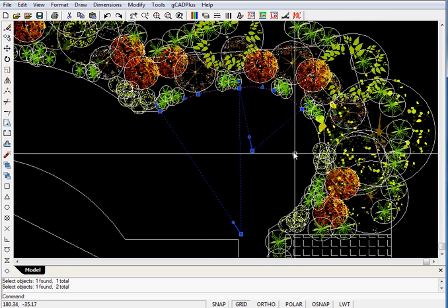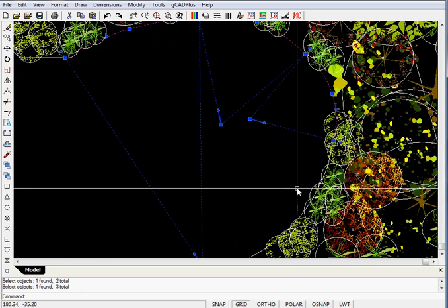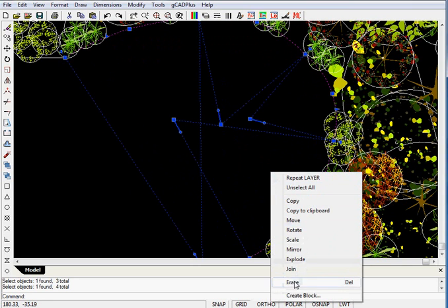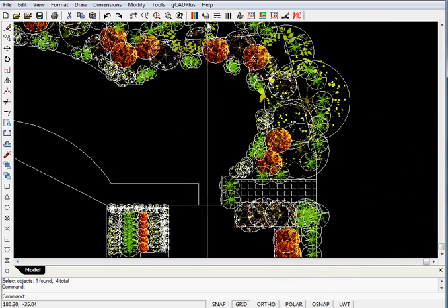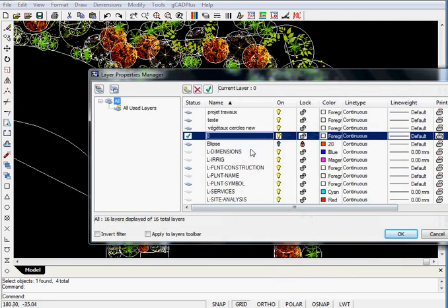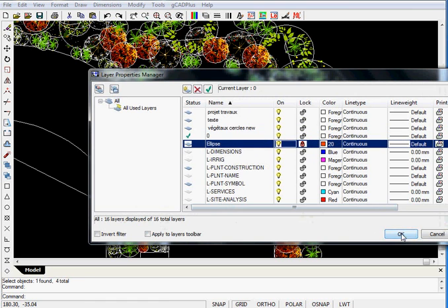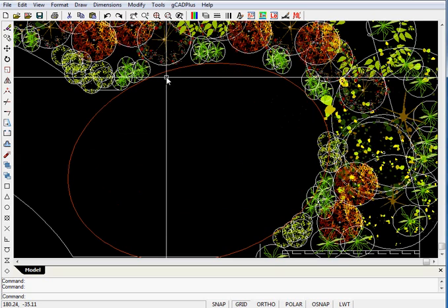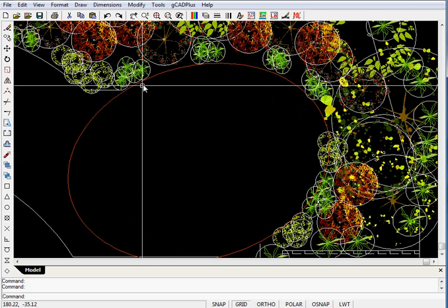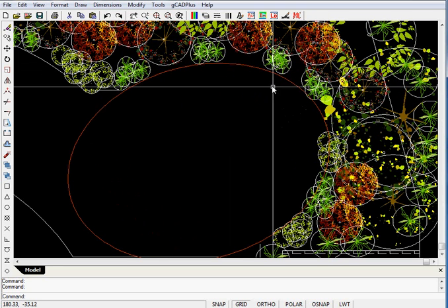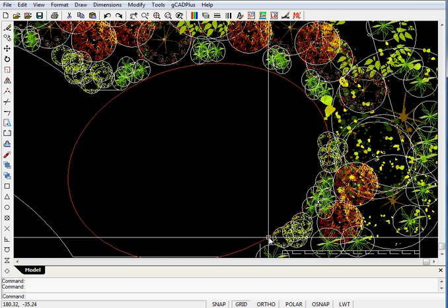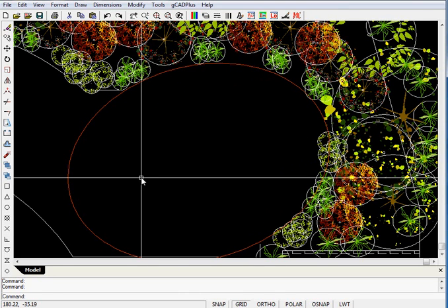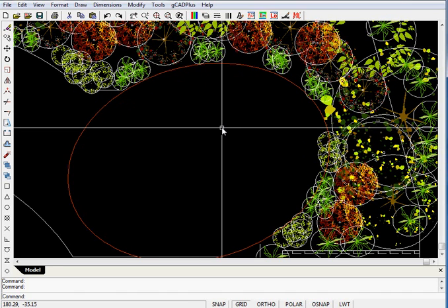So let's remove all of the arcs that are presently there, and I'll erase those. If we now turn on our layer that I've called an ellipse, and you notice that I've locked it, turn it on now, an ellipse shows through here. So what I could now do is use the point command to set a few points around here that will enable us to draw a polyline, a rather smoother polyline, we would hope, than the one we already have. You could also use it to put some arcs through here if you like.